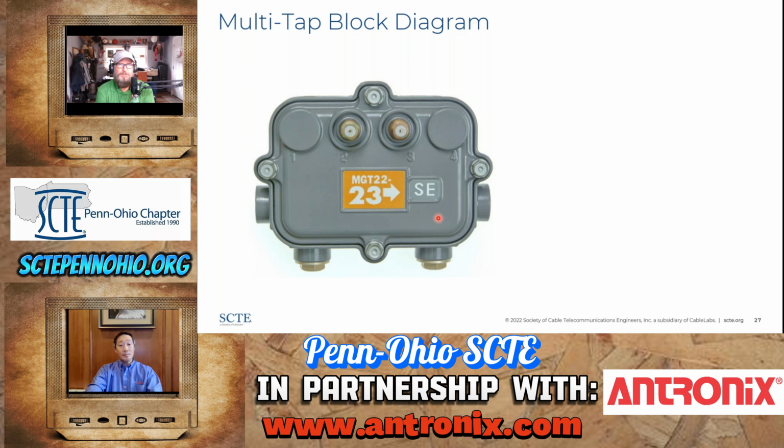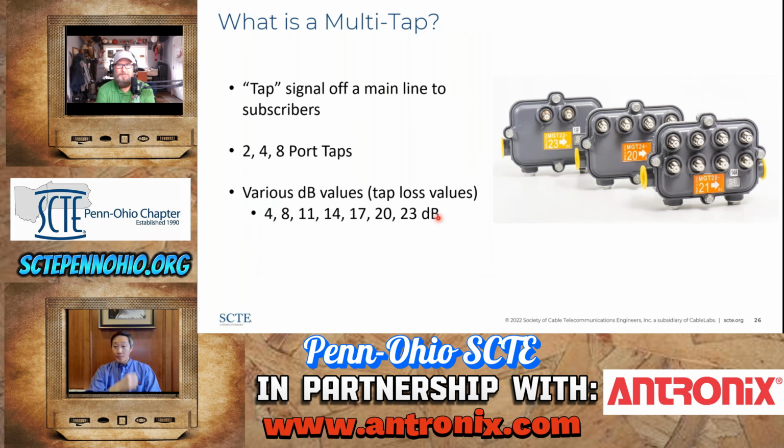Let's talk about that one for just a second. In today's networks, a 23 tap is what we would consider a high value tap. But 20 years ago, in systems that were one-way only and didn't have any return or upstream path loss considerations, we used to see tap values a lot higher than that, didn't we?